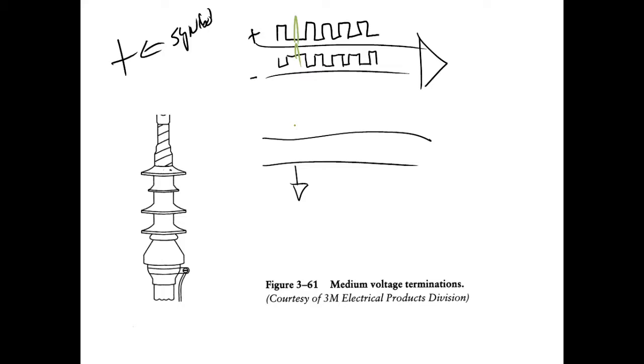It's basically done away with coax cables. Now we use twisted pair cables, unshielded twisted pair cables, right? Because it uses differential signaling. USB is differential signaling. Ethernet is differential signaling. Serial ATA, which is the new hard drive interface, is differential signaling. We can send extremely fast data with very little concern for EMI.